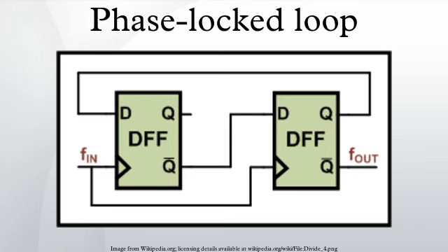Feedback path and optional divider. PLLs may include a divider between the oscillator and the feedback input to the phase detector to produce a frequency synthesizer. A programmable divider is particularly useful in radio transmitter applications, since a large number of transmit frequencies can be produced from a single stable, accurate, but expensive, quartz crystal controlled reference oscillator.